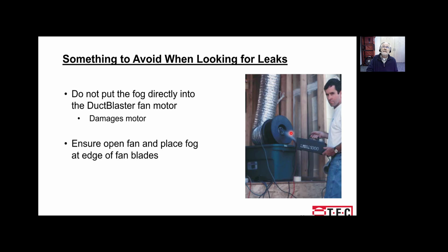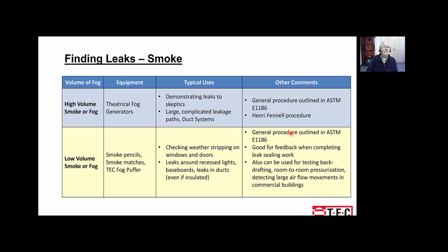But we've seen lots of fans come back where people have injected the fog into the motor and it's destroyed the motor over time. So next we're going to talk about more low volume smoke. So we're now talking about smoke pencils, smoke matches, fog puffers, and so on. And this is particularly a good technique for somebody that's actually doing air sealing work to be able to see and prove to yourself that you actually fixed the leak.